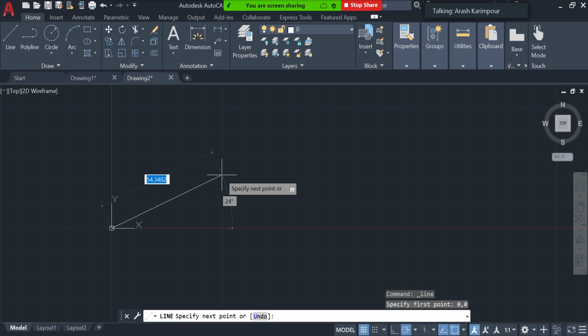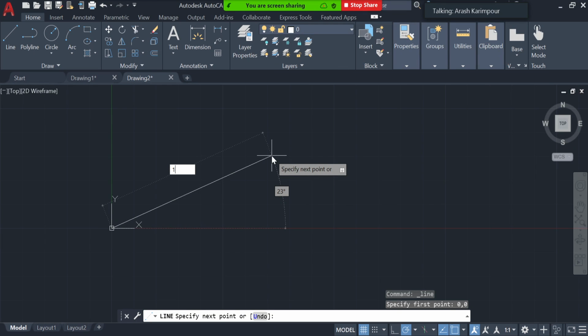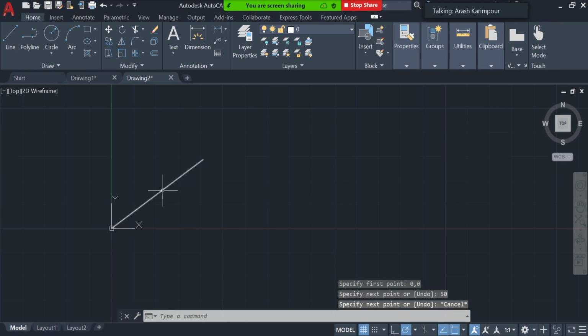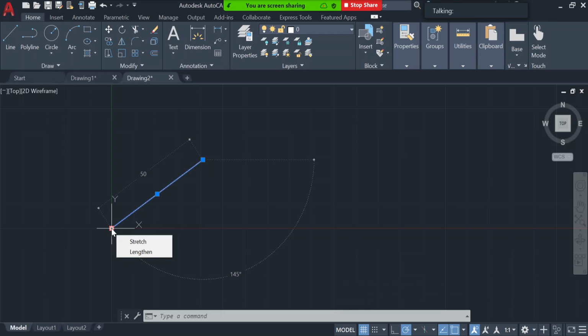Then press enter. The same here: assume I want the length to be 100 and the angle to be 35, and then I find out I probably made a mistake. If I keep pressing the tab, it will switch between these two numbers. So I can go there and, for example, change that to 50 before I press enter, and then it's going to draw the line with a length of 50 and a 35 degree angle. This is another way you can fix it. Before you press enter, if you keep pressing the tab, it will let you update the numbers that you have.